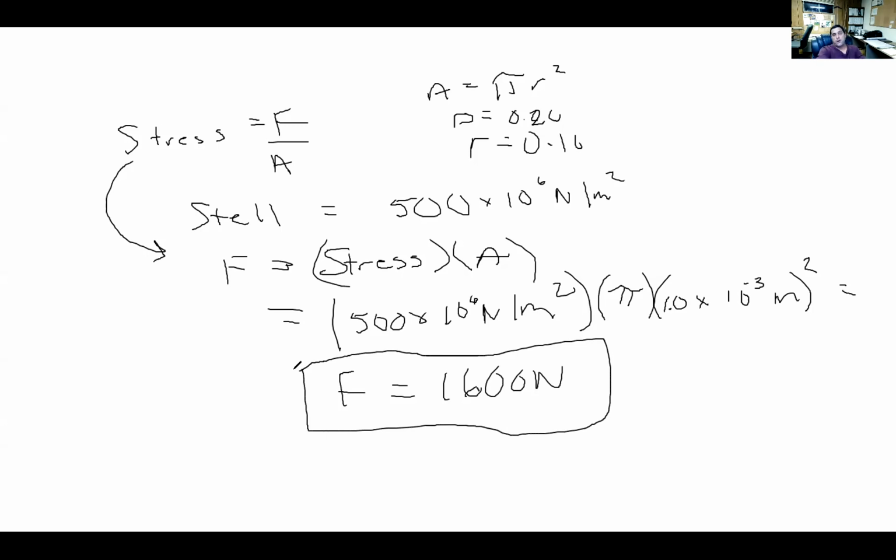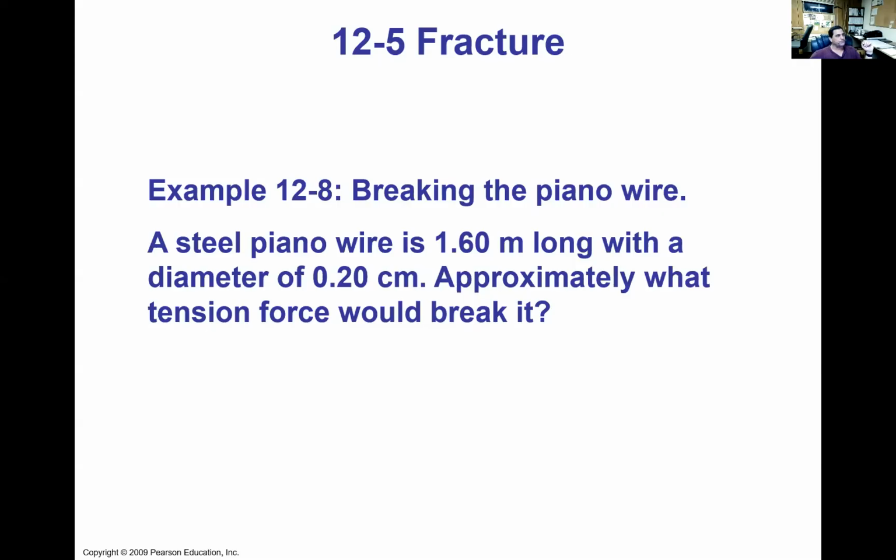Now, in the practical real world, you wouldn't want to put that piano wire in a situation where it was taking any more than, let's say, 800 newtons of force. And the reason for that is because of factor of safety. You do not want to put it in a situation where you're designing right up to the breaking point of whatever it is.